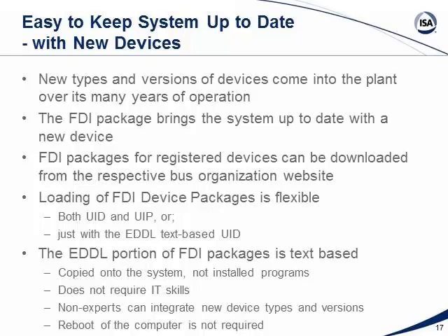They provide those downloads, so you do not have to put it in manually from a data package within the box, only just a link and you get it. Loading of FDI device packages is flexible. Both device pages and plug-in, or just with the EDDL text-based device pages. The EDDL portion of FDI packages is text-based, with no operating system dependencies. Copied onto the system, not installed, it's not a program.